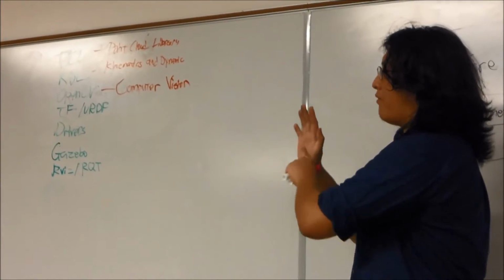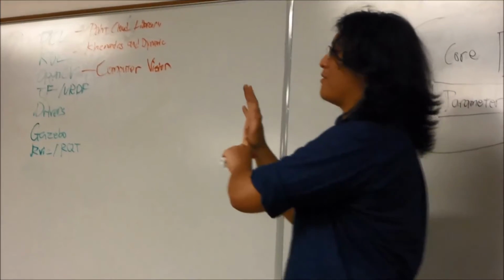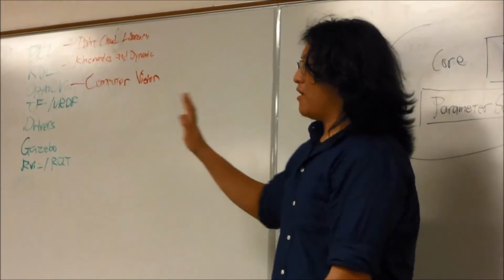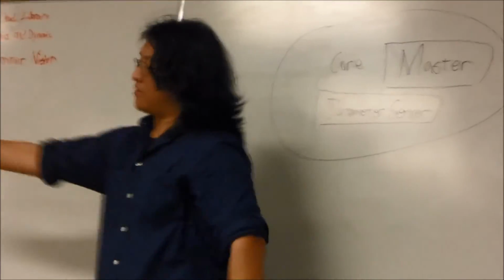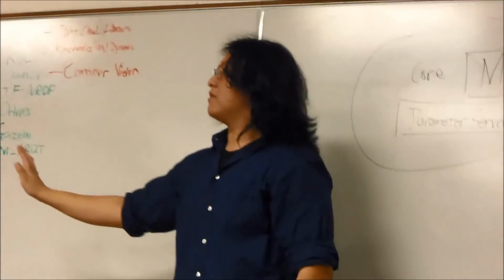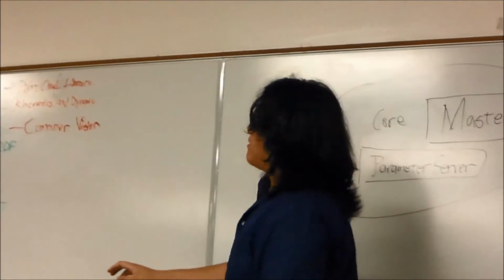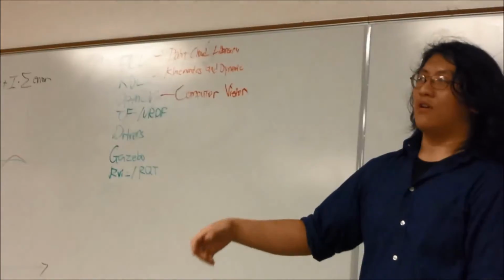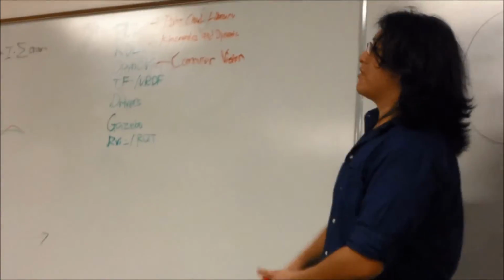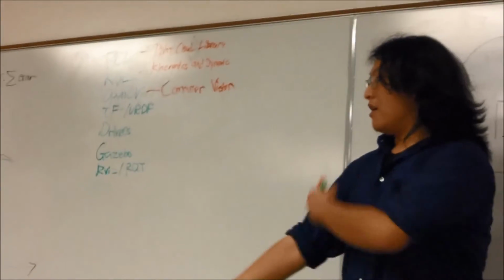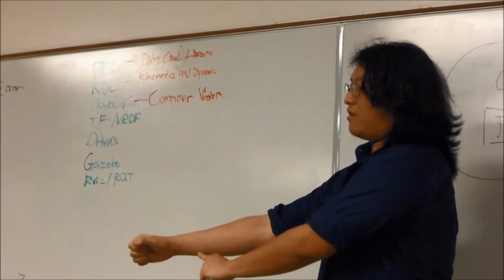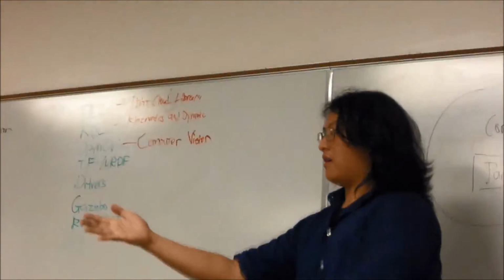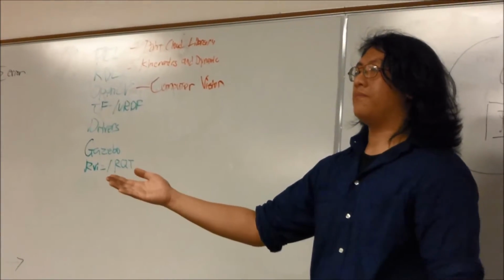If I want to apply one force, one Newton of force in that direction, what kind of forces do I need to output on my joints to output that 1 Newton? Those are the inverse calculations, which are a lot more complicated than the forward ones. And of course, it also does the forward ones, which are much easier. Given that this joint is here, this joint is here, this joint is here, where does my end effector tool frame end up in space?